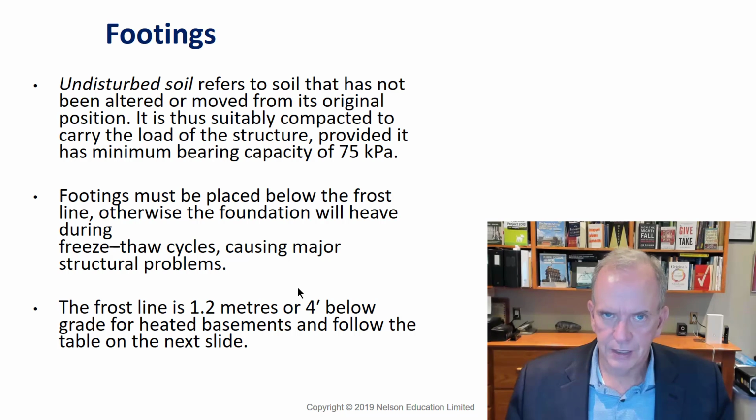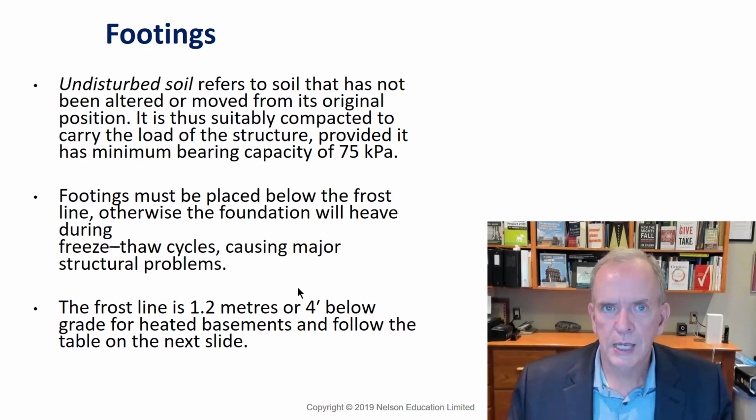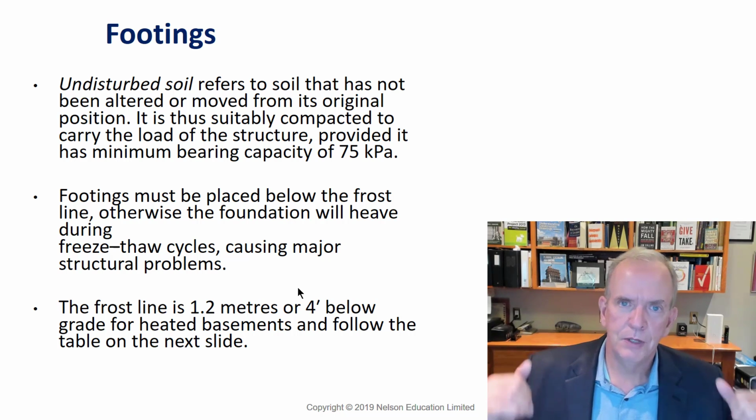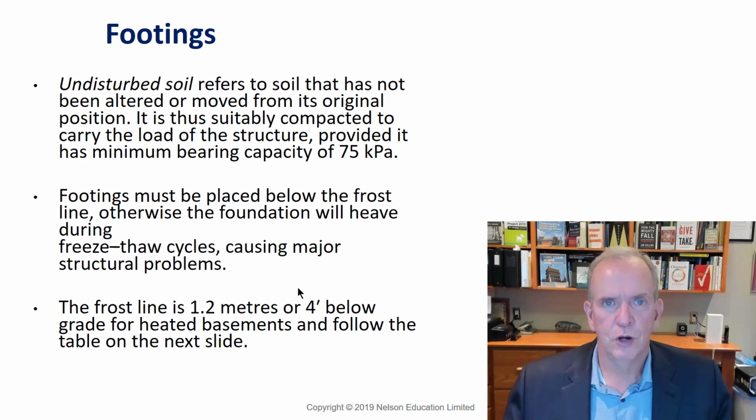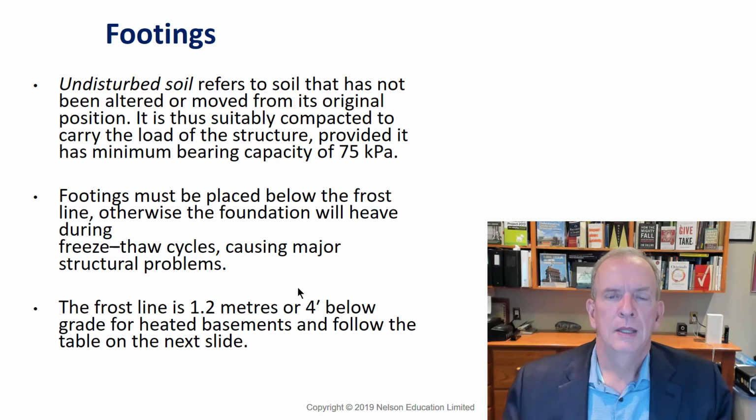Frost can move anything. It would heave a foundation. Weekend warriors, as they say, go back and add a room or a porch onto the back of the house, and they don't go down 4 feet. After a number of years, you can see this in a lot of the old parts of Toronto, with garages and porches added on the back. They're all twisted and up and down and all over the place. They didn't go to undisturbed soil, and they didn't go down 4 feet, typically.